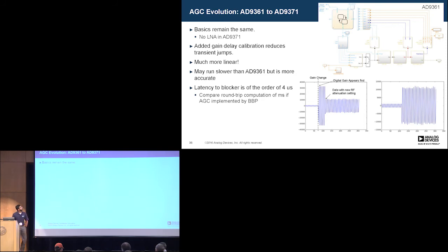Okay, I'm almost done here with the AGC. Really it is the same. This is a SIM-RF model for the 9361 AGC. You still have pretty much the same sort of action. The gain control happens at a single block, but can affect the front end, can look at the power level in between after one of the HB2 filters, and decide when to attack and when to recover.